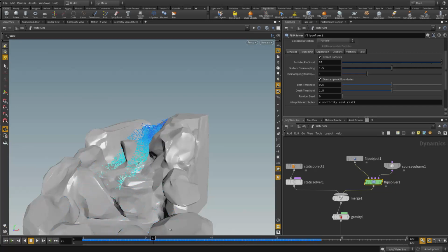So yeah, if you want more particles to really mesh out a solid, rich and fat geometry, you can crank that value up. 8 is generally good again, but maybe I can change it to 12 so that I'm having just a little bit more particles to work with.